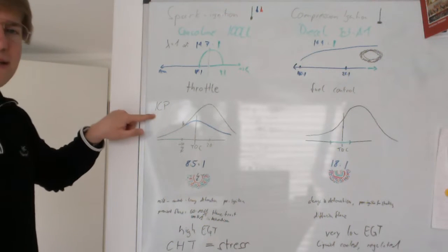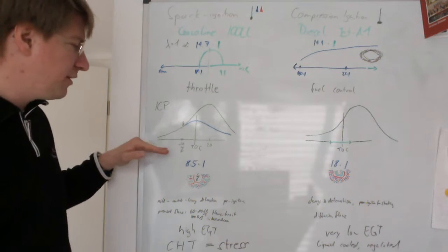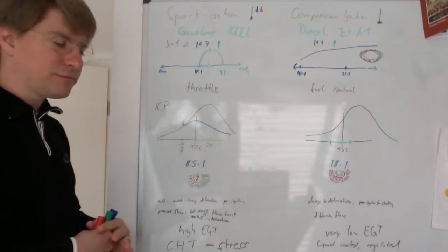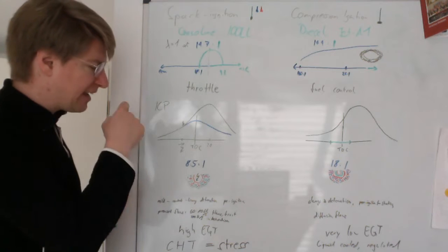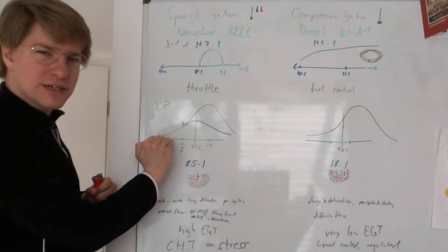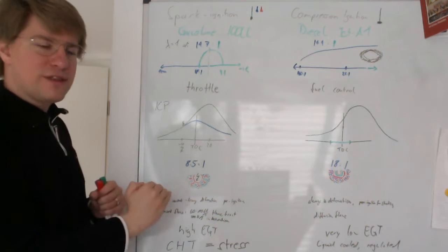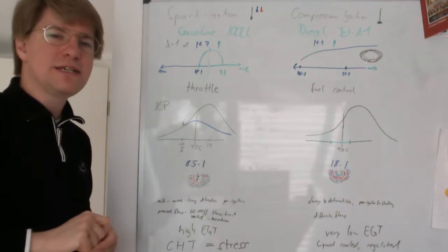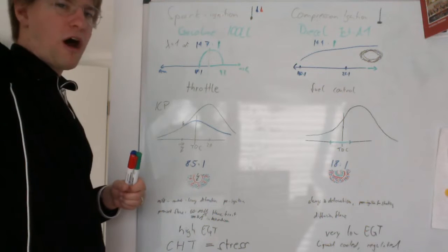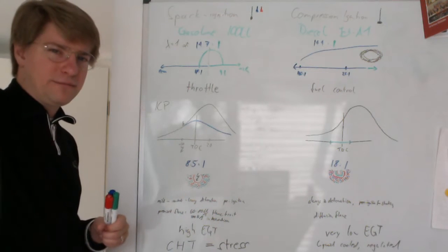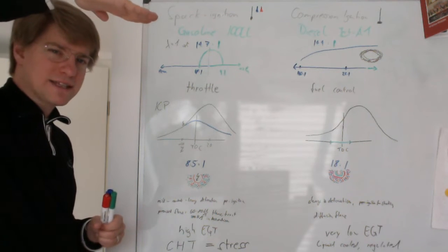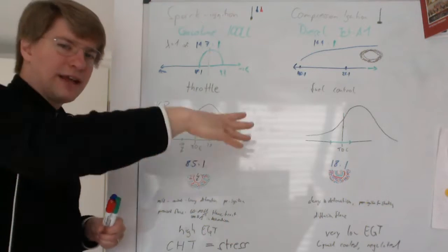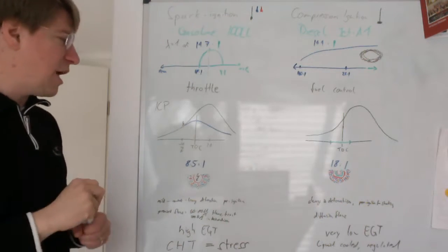What I've plotted here is the internal cylinder pressure over the crankshaft angle. So what you see here, the piston is coming up for the compression stroke, and at this line here, which is labeled TDC, top dead center, the piston tops out at the highest setting it'll go, and then in the power stroke, of course, the piston moves down again.